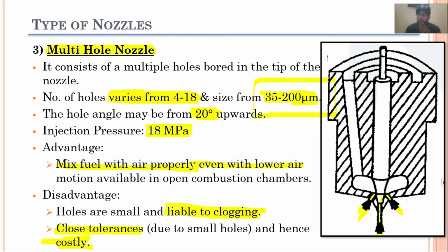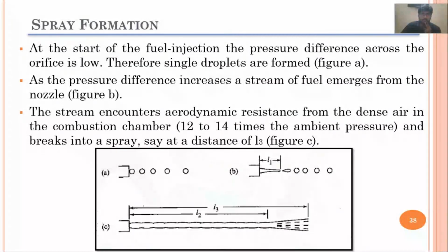I had two IC engines in the National Refinery, the first one was of 7.2 megawatts and the other was of 4.2 megawatts, and this is what we usually do during startup. We use gas for the startup, and when the engine has started operating and we shift it to full load for the production of electricity, we convert the fuel from gas to diesel.